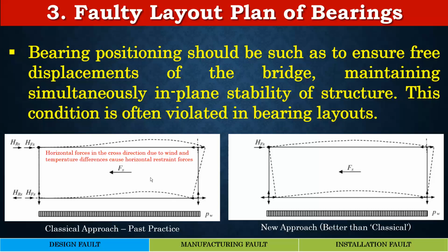The better option or the new approach is to have a free bearing here instead of a guided bearing. And you can see that if you do that, then there is no doubt that the entire horizontal load has to be taken by the fixed bearing, but there is symmetricity in the lateral deflections, and there is no ambiguity as far as the load share is concerned. So this is better, but this is not the best.